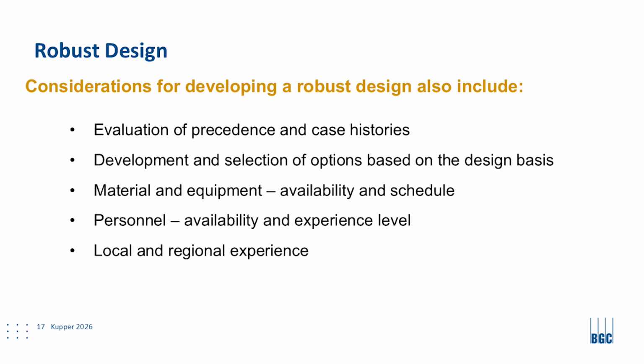So there are other considerations that we need to address for a robust design, and one of them is serviceability. Just because a design has a factor of safety of 1.3 doesn't mean you're happy, because it may not work if the deformations are too large. Or a foundation may not have failed, but it has settled so much that it's not meeting its intent.